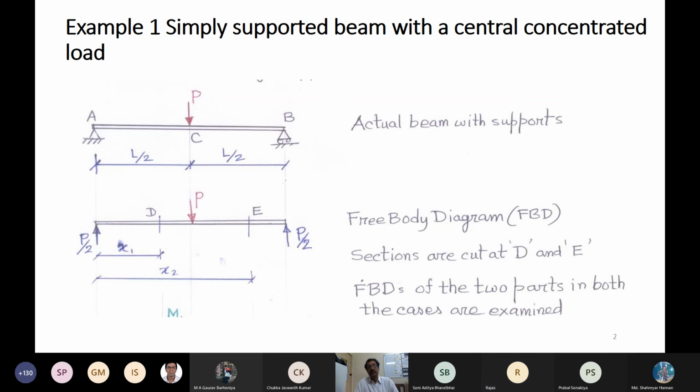It is the element, what the force is trying to do. What I tell you, you draw this figure on the plane of paper. Then you put your palm to cover the whole figure. Then gradually expose this, moving your palm. Okay. Then what you see is this P by 2 force is trying to rotate it this way. So the moment you have considered, you can imagine when in a section you look towards your right, you have this M. Can you remember the first figure M? That was positive. That is why this P by 2 is positive.